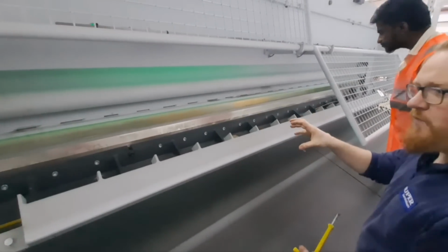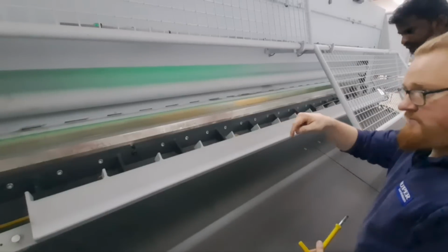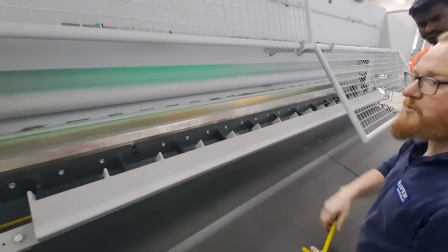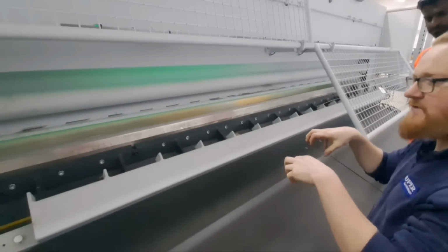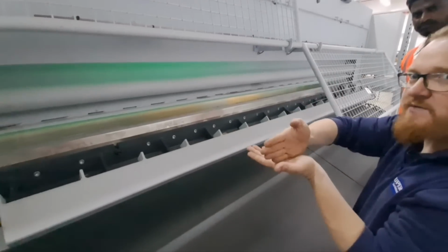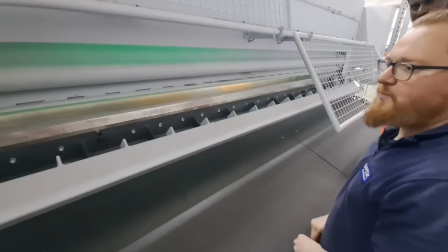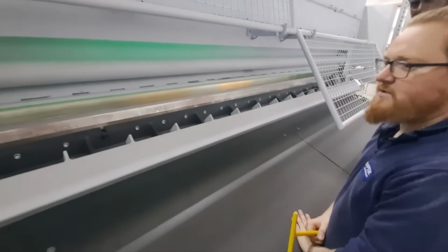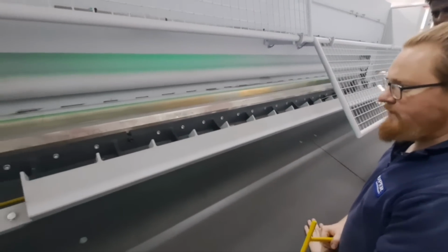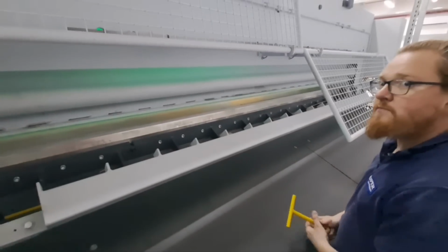When you bring in the new one, you should clean underneath it very well, because if you still have a little bit of dust underneath it and the blade is on the dust, then the angle isn't correct and it's getting a little bit difficult to adjust it properly. Yeah. And it has a resting point?